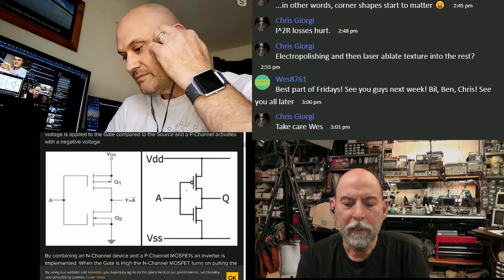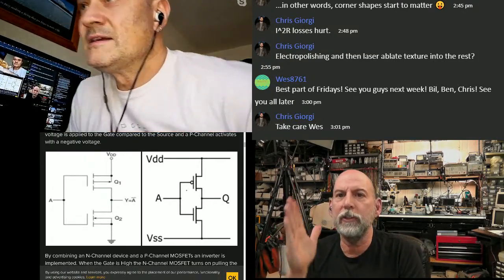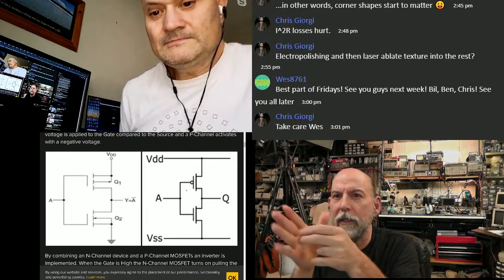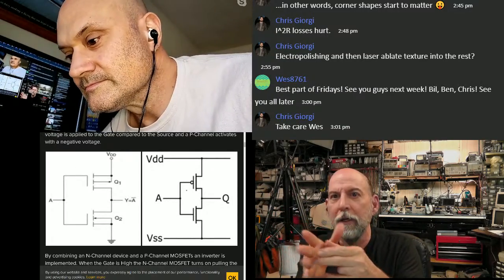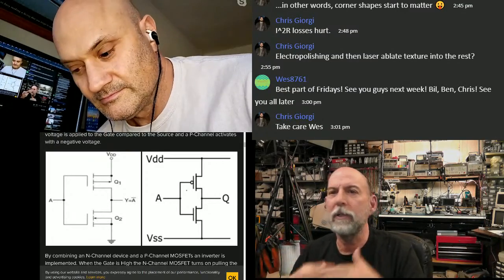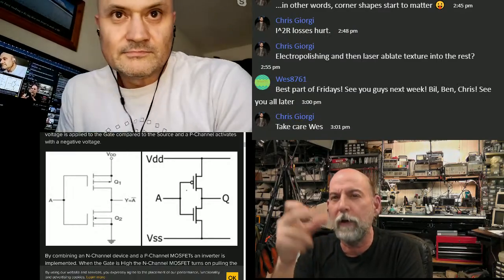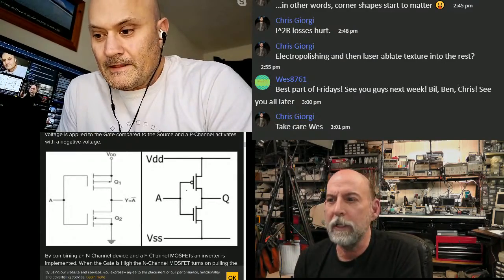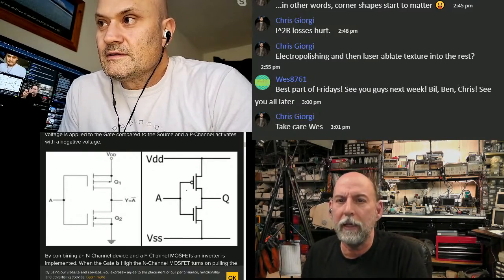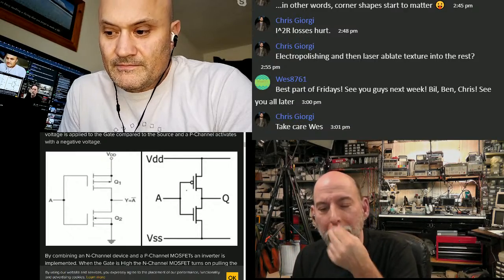Right, right. Now, there's an instance where we do reference the edge sometimes, and we try and do it in the drawing. And that is if there's a connector that has to line up with a housing hole or something, we'll call it out as a detail. I don't know if the PCB vendor does anything different, but what we say is, look, this has to be like 0.04 from the edge, and in a detail, because if the tolerance goes up too high compared to the edge or the standoffs, then the connector hole won't line up.